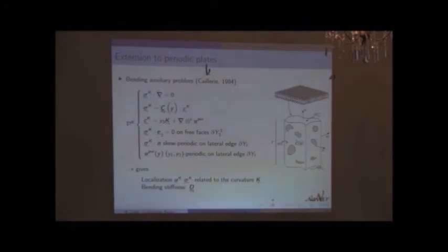If you solve this bending auxiliary problem, you will find a localization tensor related to the bending stress, but it's a 3D stress. It's not purely in-plane now. This was done by Kairi some time ago, and I think he proved the convergence result on that, because these procedures lead to the Kirchhoff plate model, and so you can homogenize the periodic plates as a Kirchhoff plate. But we want to get the effect of transverse shear, or the effects of the generalized shear force.